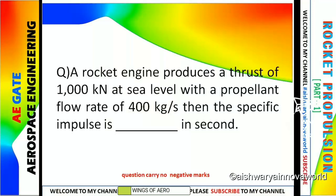Let's go to the next problem. A rocket engine produces a thrust of 1 kilonewton at sea level, with a propellant flow rate of 400 kg per second, then the specific impulse is dash in seconds. Now here what things have been given? Thrust has been given and the propellant flow, see the unit kg per second, so m dot has been given, and what you have to find is specific impulse. This question carries 1 mark, and since no option, it carries no negative mark.